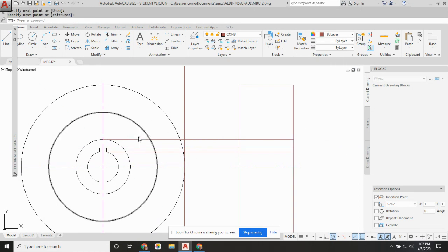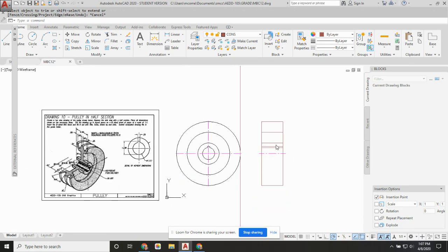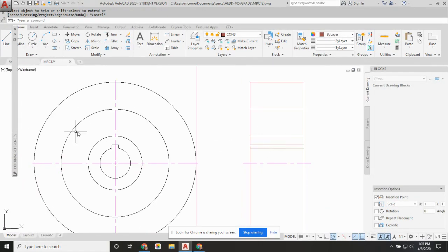Normally, if we were looking at this in a typical exterior view, these would all be hidden line features that we would see. But they're going to become object line features in this example. So this shows where the top of that hub is, and this shows where the top of the key is, and that shows where the end point here that we see at the edge of that arc would end up landing by projection. So now I've got to build the shape here.